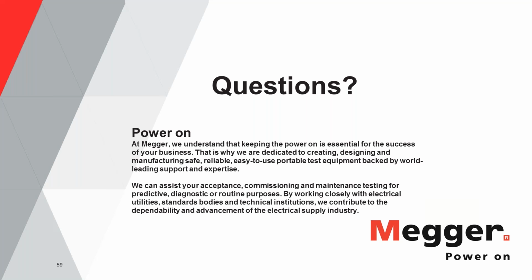Remember, when we talk about circuit breakers, you could have different types of failures. There could be a problem because of heating that could lead to problems with the contacts. There could be insulation failure, or the breaker couldn't handle the amount of current it is supposed to handle. Understanding what kind of failure those breakers had would give a little more insight. But in general, what has been seen is that primary injection testing does not, or should not, affect the life of the breaker.